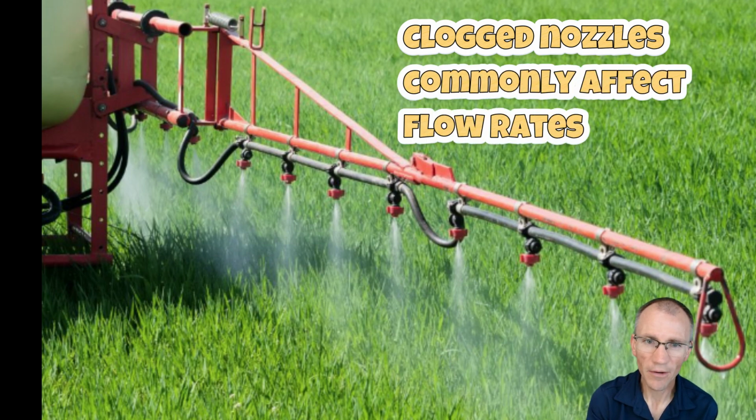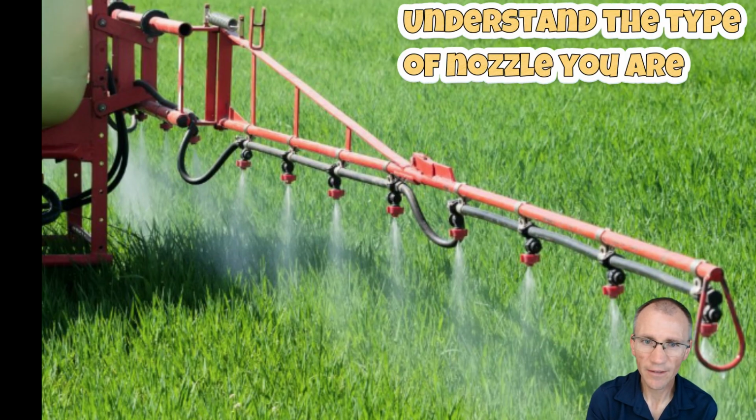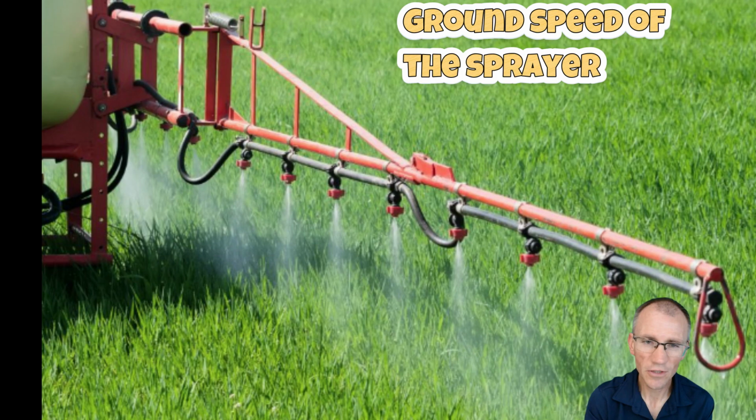Well, if you think about it, if you have pesticide buildup in your nozzles, of course you're not putting out as much of the product, so that nozzle flow rate is going to make a big difference. Now, we talked about this earlier. There's a lot of different types of nozzles you can use, so that's a whole other ballgame. You have to understand the flow rate of each individual nozzle to understand how much of the product you're going to put out. Now, as far as ground speed of the sprayer goes, there's another one.